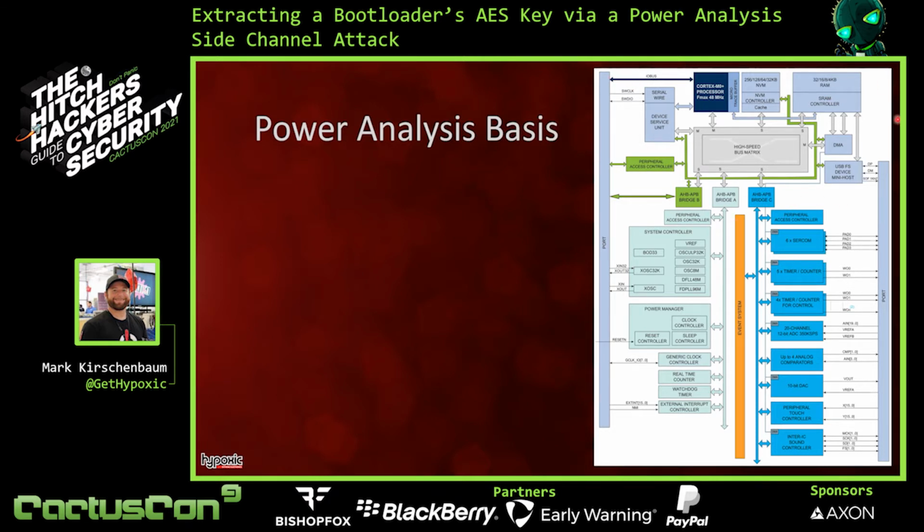The Cortex M0 Plus is actually a von Neumann architecture, so it's got a shared high-speed data bus. And we'll see this as the data from RAM is going to go across this high-speed data bus. The data from flash, internal flash, or they call it NVM, likewise is going to go across this bus. So there's some kind of caching in this Cortex M0. They don't really break it out here in this diagram. There's also going to be the registers like R0 through whatever. And more or less, what we are concerned with is every time we read or write from this bus,